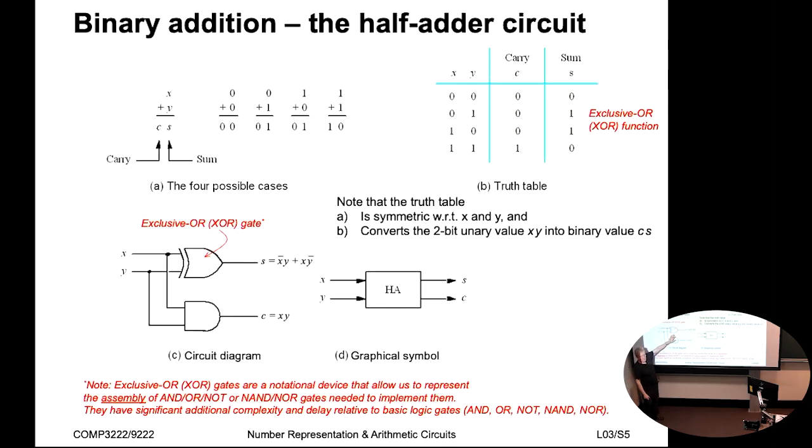It's really just a symbol that we use to represent the exclusive OR function. Because to implement this function, not x and y, or x and not y, we need two AND gates and an OR gate, right? That's a two-level function, whereas this is just a single-level AND gate, right? So it's a lot simpler.